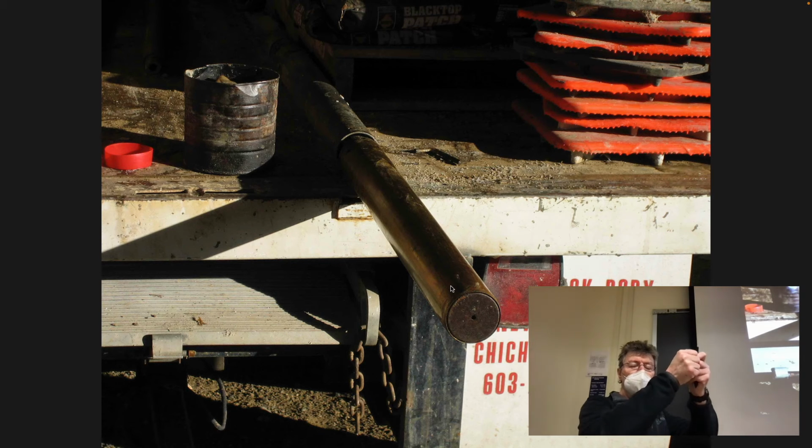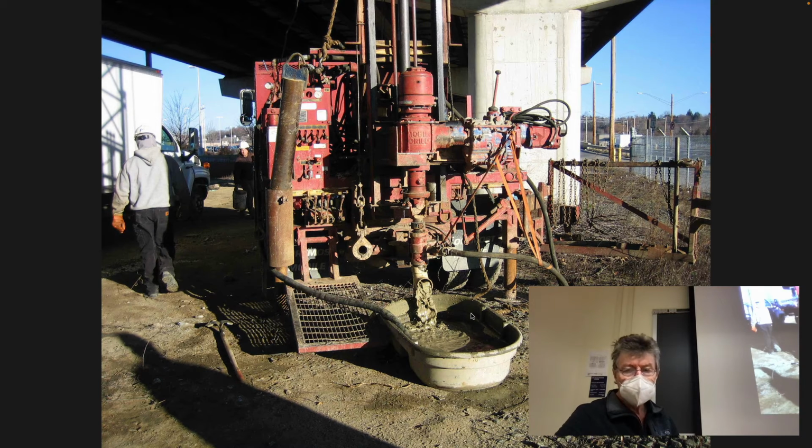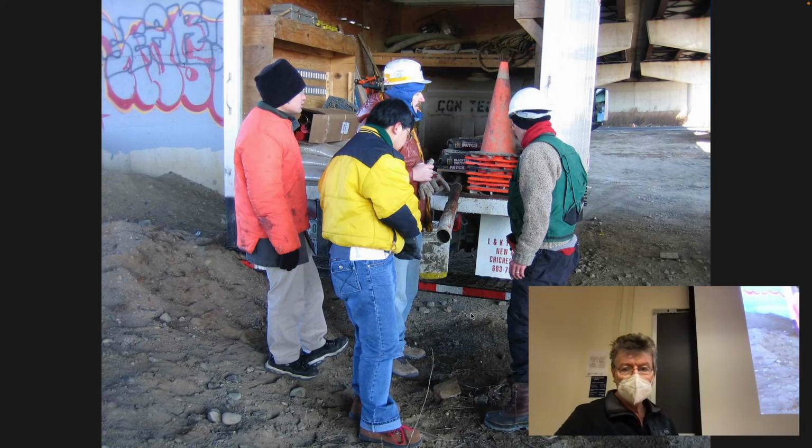It's put into the borehole, put down to the bottom, and then physically the cookie cutter is pushed into the bottom of the hole, and this piston is allowed to freely move up into the inside of this sampling tube as the sample gets pushed into it and therefore retrieves it. And the idea is if there's no air gap between the end of this piston and the top of the sample, then you have a vacuum which gives you a greater chance that you're going to recover your sample when you twist it off at the top and then the base, and then you recover it up through the open hole. And so that's a picture of the drill rig drilling.